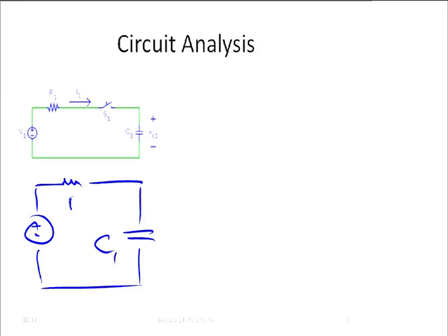Okay, so now we want to solve for the voltage VC1. So how we're going to do that? Well, why not? Let's use node voltage analysis. For which nodes do we have to write an equation? Just for this one, right? VC1, the other node V1, of course, the voltage is given. So it's one single equation that we'll have to write. We'll see. In the end, we're going to end up with two, but essentially it's one single equation.